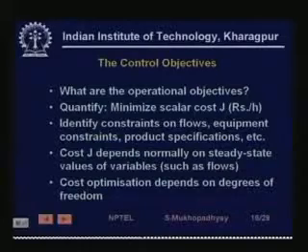Now, this cost optimization, to what extent it is possible, depends on the degrees of freedom. Now, what are the degrees of freedom? It tries to answer this question: suppose you say, okay, this is the plant, these are the governing equations, these are the things which can be manipulated, and those are the things which cannot be manipulated, they are given to us, they are disturbances, some feed coming at some flow rate or some temperature, no control on that.